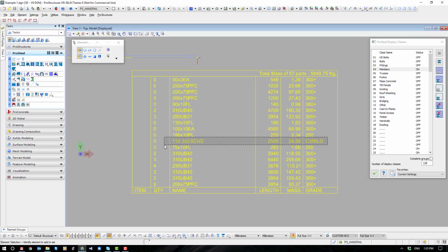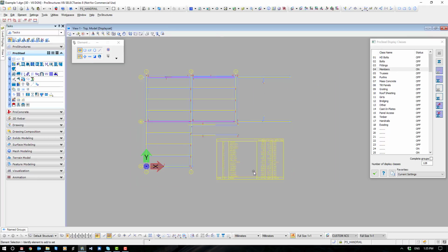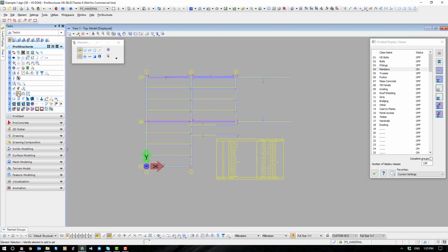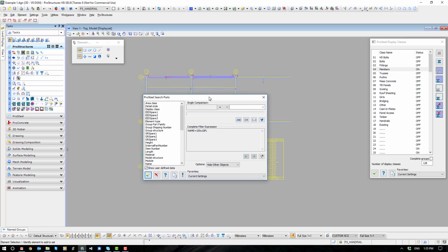Make sure that the material grade for CHS, which is hollow, has a unique material grade. That actual material grade there is fine, C350LO. So again, we're checking material grades and things like that as well. So using a ProStructures search, we will go and find our plate. Okay, so I'm going to scan the model, and that's going to grab all the information out of the model and populate my search criteria here.